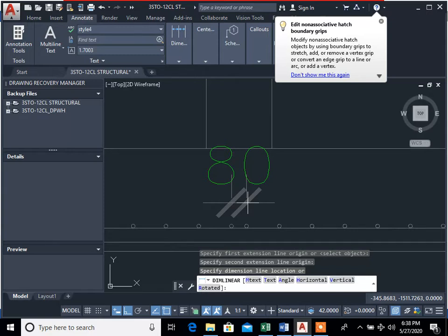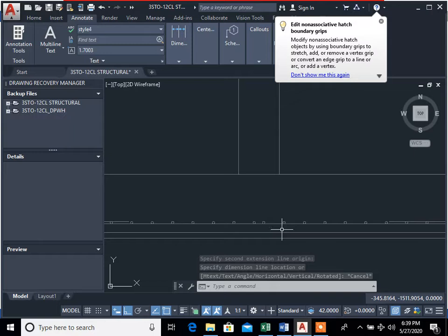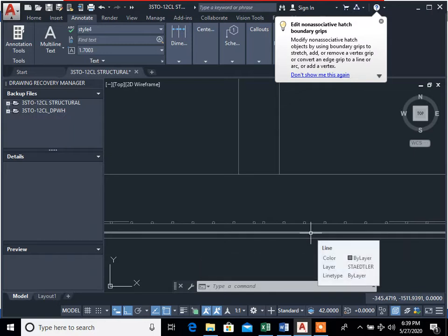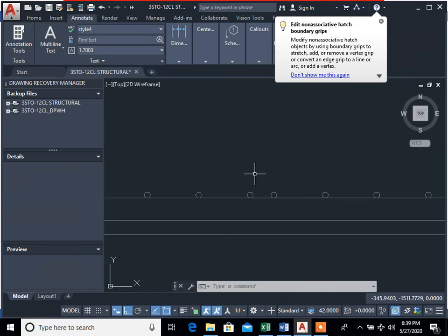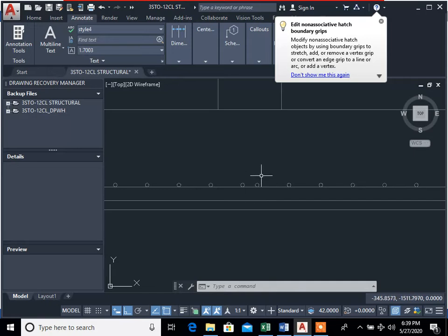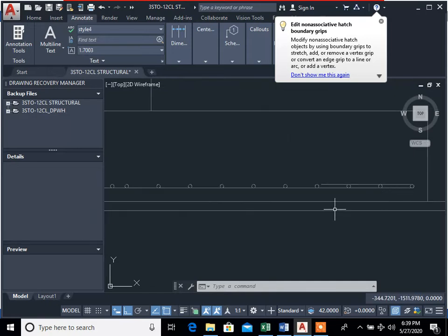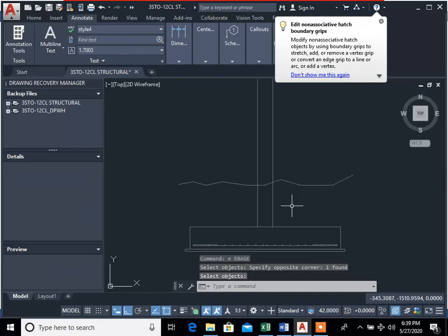I think it's okay, since based on the structural code of the Philippines, the smallest spacing of the rebars must be around 25 mm. So ayan, papasok naman yung rebar dyan, or the gravel can pass through this type of spacing. So ayan. Then next, alis natin to.